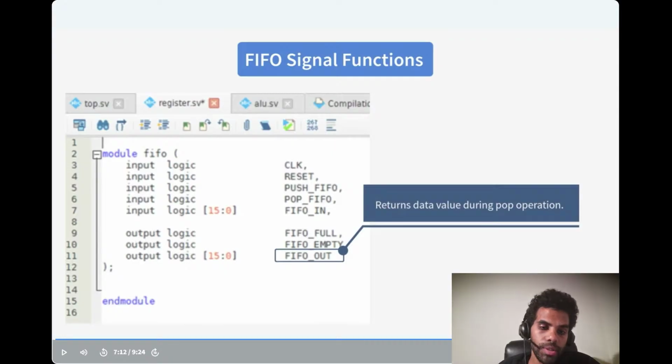So you want to push something, you want to pop it, and you want to write data to be pushed, or the data that is read outside from it, in order to give a signal when the FIFO is full, or a signal when the FIFO is empty.